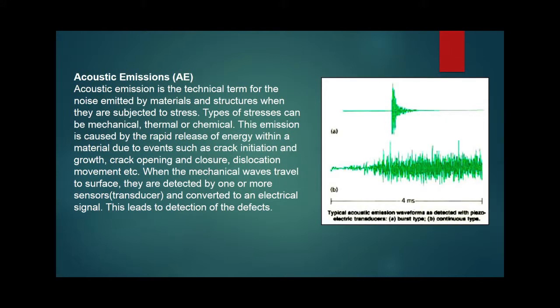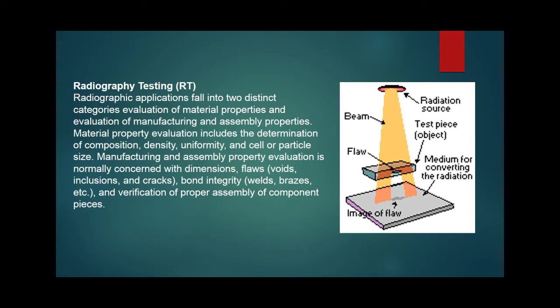Acoustic emission testing, AE or AET, is a non-destructive testing method that's used to analyze emitted sound waves caused by rapid release of energy due to defects and flaws. These acoustic waves are produced by small deformations, corrosion, or cracking, which can occur prior to structure failure. AET is a method which evaluates the elastic waves caused by defects formed within the specimen. AET is often used to monitor items like pipelines, bridges, and cables. It can also be continuously used in monitoring structures such as mines.